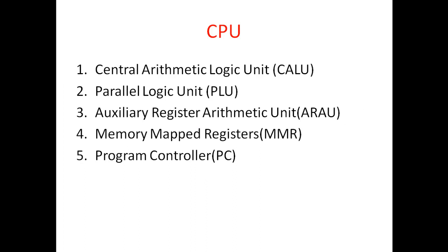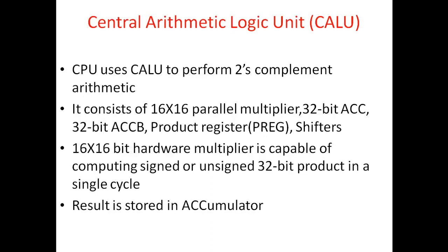Central processing unit. It consists of central arithmetic logic unit called CALU, parallel logic unit called PLU, auxiliary register arithmetic units called ARAU, memory mapped register called MMR, program controller called PC. Let us see one by one.